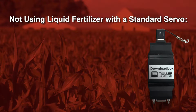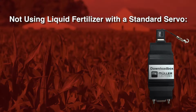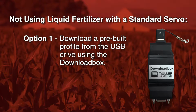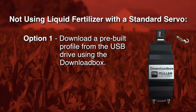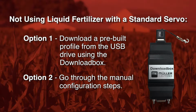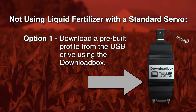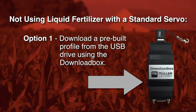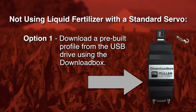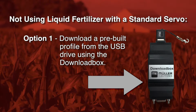If the liquid fertilizer with a standard servo is not applicable for your use, you have two options. Option 1, download a pre-built profile from the USB drive using the download box. Option 2, go through manual configuration. Option 1 requires the download box. Please refer to the Download Box Operating Instruction Manual or watch the Download Box Operating video. Both of these resources will provide you with step-by-step instructions to upload the proper ECU profile.